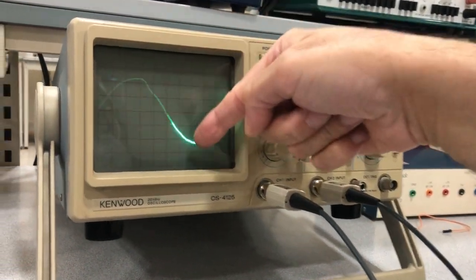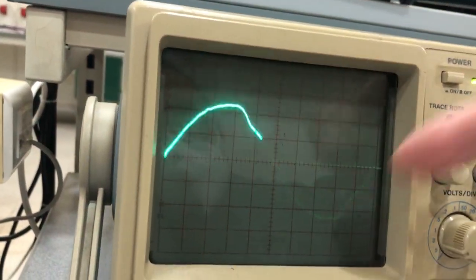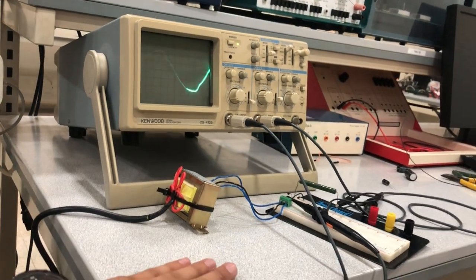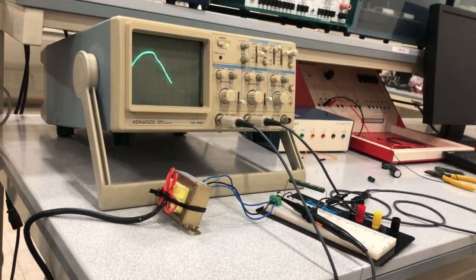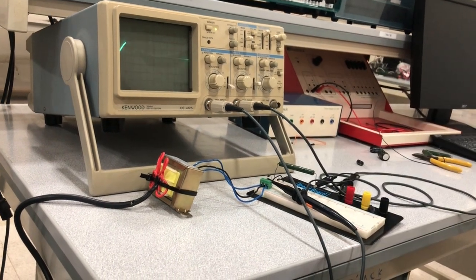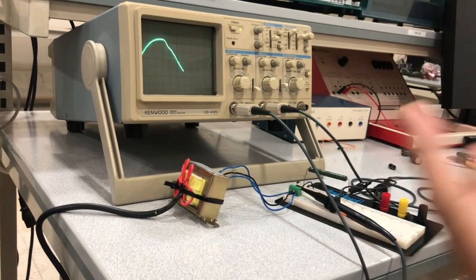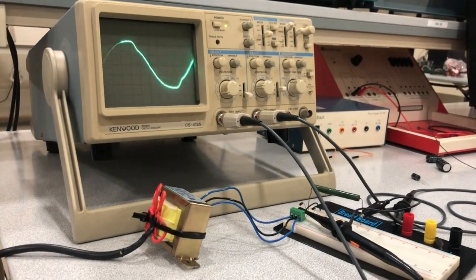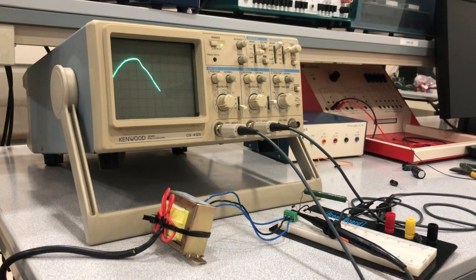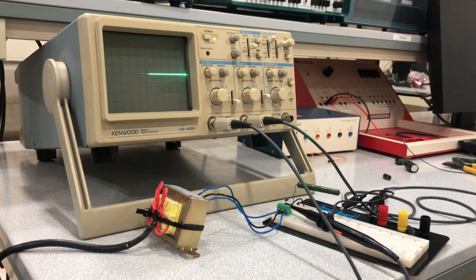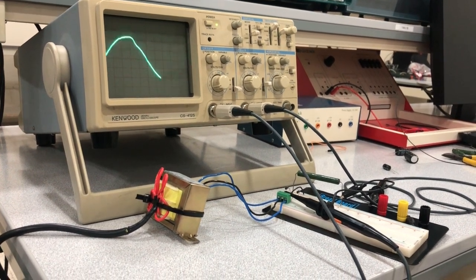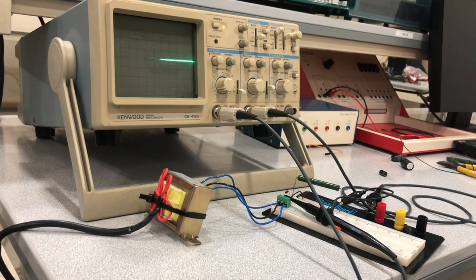Now, why this is not a pure sine wave is because the loads in the university are electronic loads, the power supplies of the PCs mainly. They are not resistive loads. They have a bridge and capacitor just like this, and the current peaks only at the peak, and this is what creates distortion on the signal coming out of the generator or the power that is coming out. It's a voltage signal anyway. And this is all due to not having pure resistive loads. And the current is not sinusoidal, just like the voltage is.